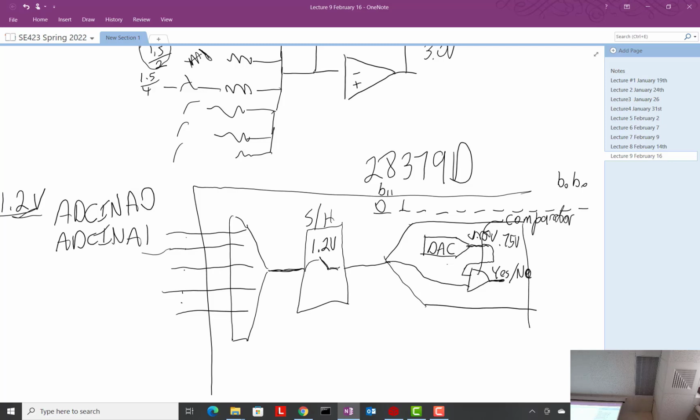And it goes to the next bit. All right, and it sets this one and tries. Well, what's 0.75 plus 0.375? That's 1 point something, right? What is that? Anybody got a calculator quick? 1.25, is that what it is? Great. Thank you. So now, what we are outputting right here on the DAC is 1.25.